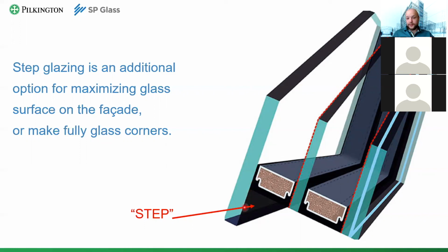Alternatively, you can paint it with the ceramic paint. Best not to use bright colors like white or something else, because then you will have a distinct difference between this zone and this zone, because primary and secondary sealant are usually black.